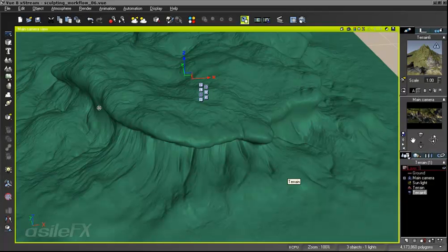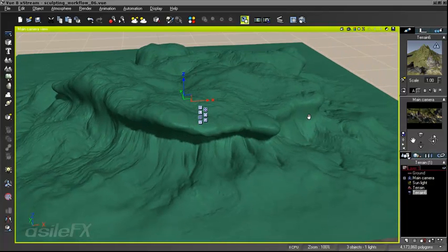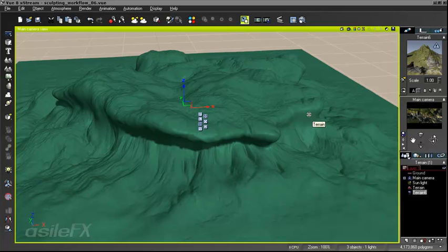At the moment, if it's sculpted and you have any sort of terrain you would possibly want to create, the UV map that's generated for it is just kind of useless. In some cases, it can be a good starting point. You might need to relax the geometry. Of course, that would be in another application. You wouldn't do that in Vue.